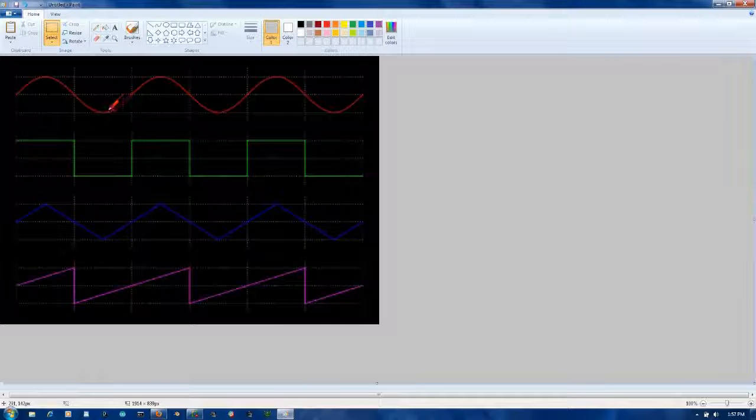So what happens is we slowly see a voltage increase until, of course, it peaks at 5 volts, and then it slowly decreases over time. So at this point here, we're actually seeing 2.5 volts, and down here it's in half again, of course, and here is 0. So our analog signal basically consists of the ability to move between many voltages. And this is going to be true for our Arduino sensors. And like I said, we're going to go over this in more detail. We're actually going to do analog to digital converters and digital to analog converters on our Arduino.